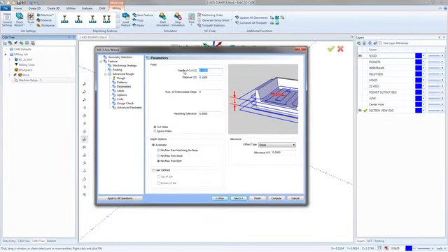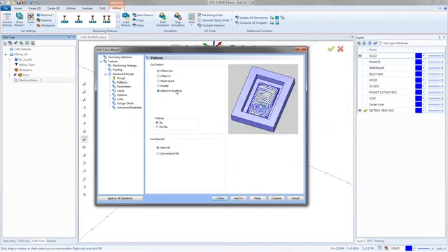Now, depth of cut. We have so many different ways, and there are different thought processes on how much material we should take off. It really depends on the actual material we're cutting. But this tool path can do it for those of you that like to be a little bit more reckless. I don't want to say reckless, but let's say you want things to run faster, you want to do things quicker. This tool path has the adaptive options. It has the high speed machining capabilities. So you can go in and give it those quick runs. You can do it with a much heavier depth of cut and a much finer step over than you'd normally do.